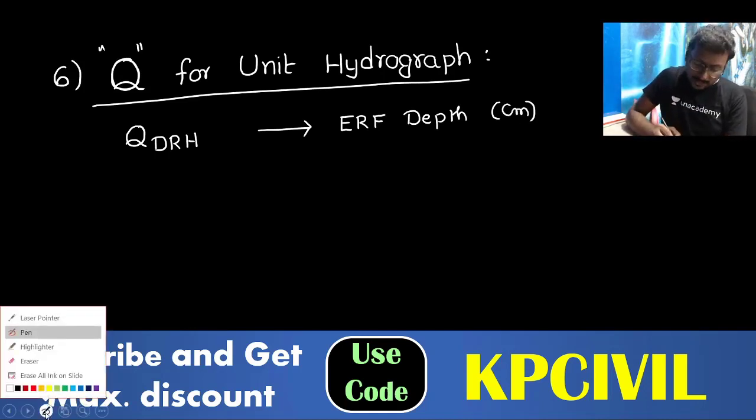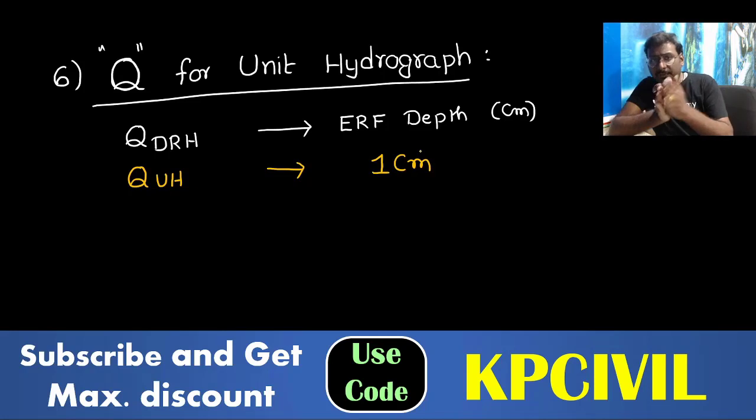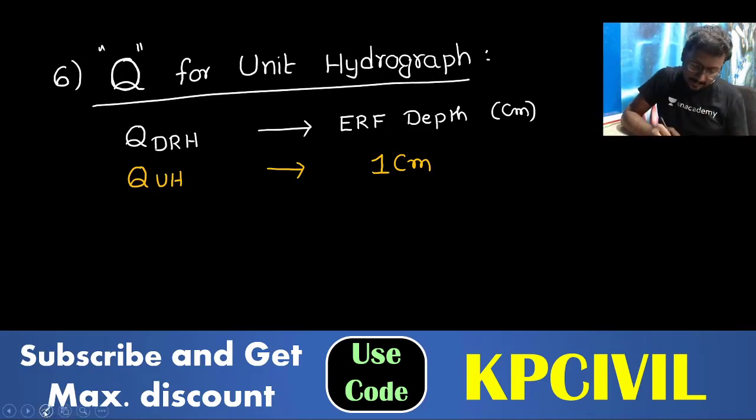Now you need the discharge ordinate of UH for what depth? UH is for what depth? For 1 centimeter depth. For an effective rainfall depth of some value, discharge is QDRH. For 1 centimeter depth, what is QUH? You understand the point? For X centimeters, discharge is QDRH. For 1 centimeter, what is discharge? Just cross multiplication.